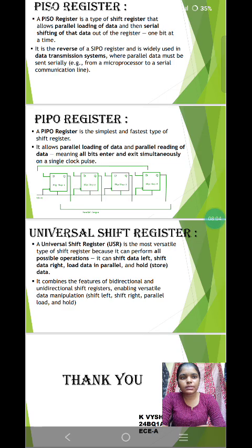Power dissipation. Resistors dissipate electrical energy as heat. The amount of power a resistor can dissipate without damage is its power rating, which is related to its physical size. Types of resistors. Resistors can be fixed with a constant resistance value or variable where the resistance can be changed. Kirchhoff's laws. These fundamental circuit laws, along with Ohm's law, are used to solve complex networks. Kirchhoff's current law: the sum of currents entering a node is equal to the sum of currents leaving it. Kirchhoff's voltage law: the sum of voltage drops and rises in any closed loop of a circuit is 0.